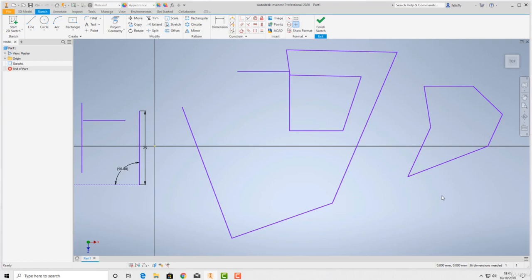If you then use that part in a complex assembly, and then later on you start changing some items and angles, Inventor will look around at the model and it will think, well, he wants to change the size of this line or this angle, but lots of things are fixed. I need to find something that isn't fixed, some geometry I can move, something where I haven't been told an angle or a length. And it will find something like this in your drawing and it will just destroy this shape in order to make something else work.